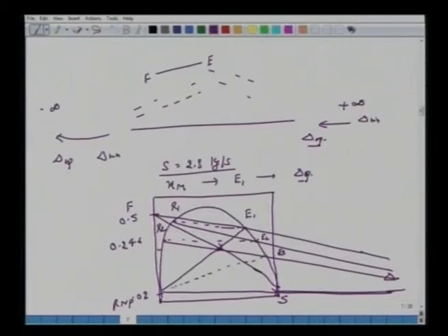The number of stages is greater than 2, or it is 3, so it has gone below this RNP equal to 0.022%. Okay, so that was an example on multi-stage counter current extraction, where we try to find out how many stages are required and what is the minimum amount of solvent required. So it's a very peculiar example where we have two types of tie lines, in which case del min can fall on the left hand side, del min can fall on the right hand side. One has to calculate the worst case.